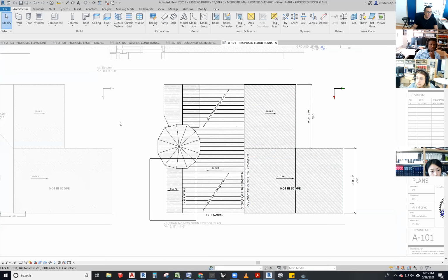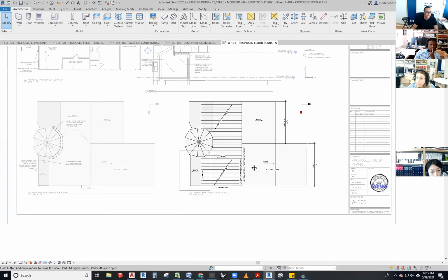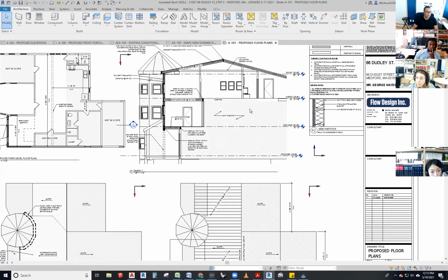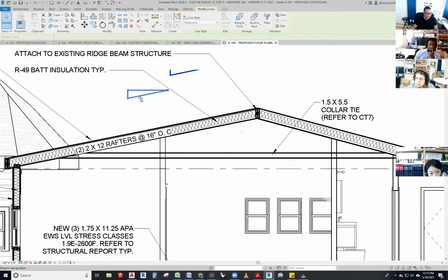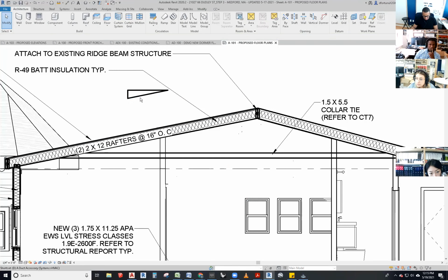What's the pitch of this roof? I'm going to go into section very quickly, and he told me I think it was 6 and 12. So what's the pitch of this? I basically just draw this triangle. That's just my way of doing this. And then I give it, it's always 12 and something, right? So I'm going to make this 1 foot.